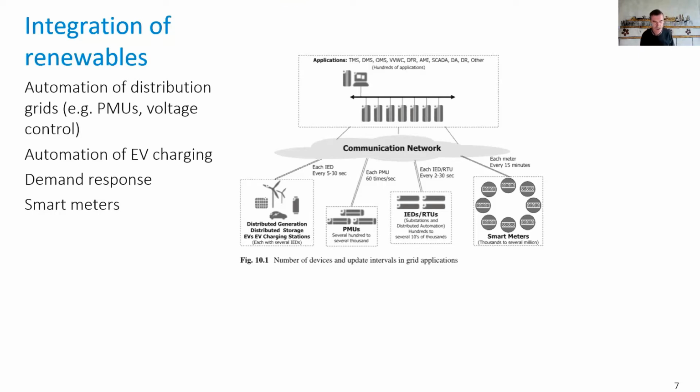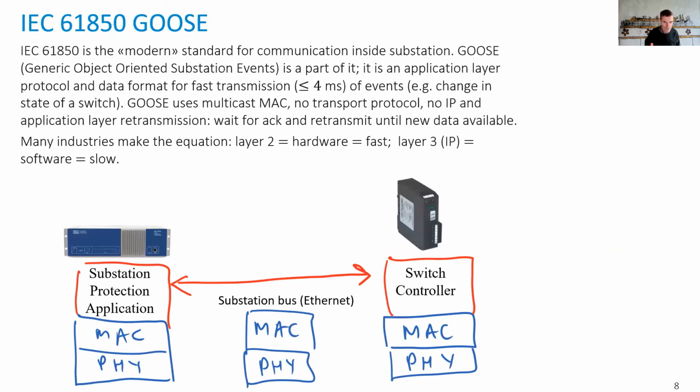That's called a ramp of the consumption that occurs within 1 or 2 hours. So you need to start huge amounts of resource during a short period of time. That costs a lot of money. So an alternative is also to modulate the consumption, for example, by, if you have electric cars, to leverage them to avoid this peak and thus reduce the costs of the reintegration of renewables. So the smart grid, because of that, is at the heart of the integration of renewable. If we want a grid that lives on a large fraction of renewables, we will need to do such things.